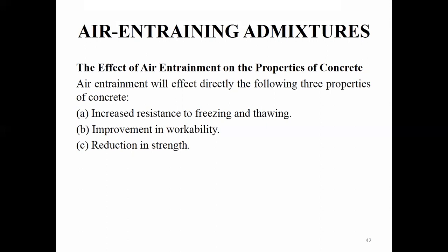So as a result, what happens? One half to two thirds of the air content in the fresh concrete will be driven out, depending on the time duration and water cement ratio. This improvement in the workability of air entrained concrete can also be attributed to the lubricating effect of the microscopic bubbles between the fine aggregate, and it also provides some cushioning effect between the grains of sand. Therefore it reduces the particle interference to a minimum.